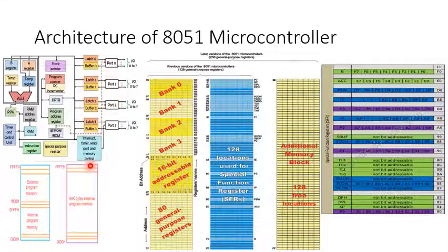Internal ROM. The data memory and program code memory are in different physical memories, but both have the same address. An internal ROM occupies addresses from 000H to 0FFH. The program counter addresses program code from 000H to 0FFH. A program address higher than 0FFH that exceeds the internal ROM capacity will cause the 8051 architecture to fetch code bytes from external program memory.